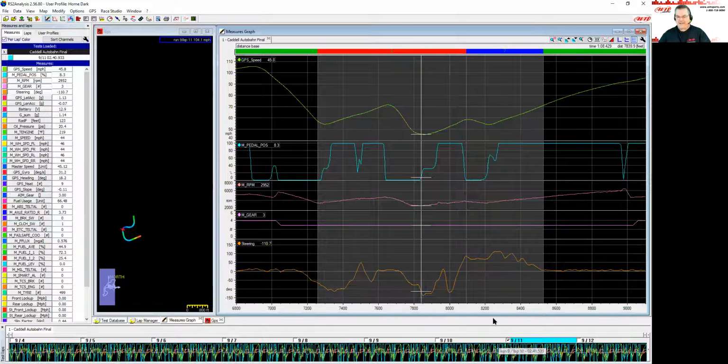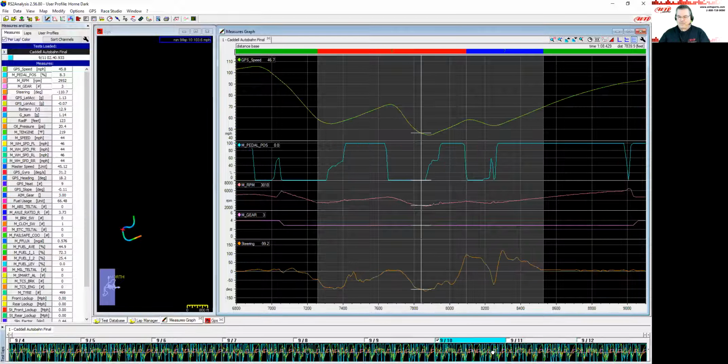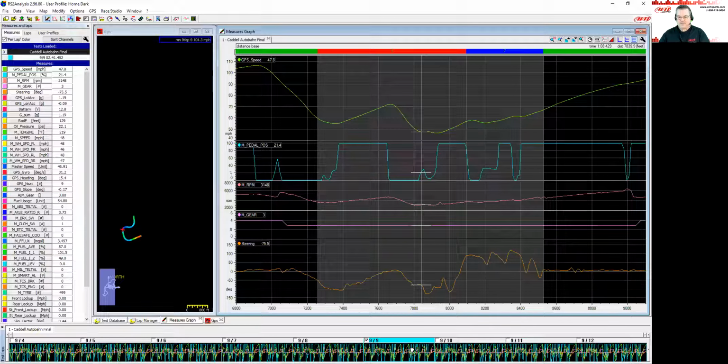How did the driver get back on the throttle on this little short corner right here? I take my eye, and my eye stays looking at the data, and then I take my cursor down to the Lapse toolbar down below, and I just push and hold my left mouse button, and I'm just looking at individual laps real quickly. This one here, you see the driver started to get after the throttle and then had to get back out of it and get back after it.